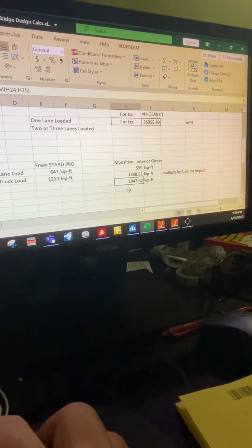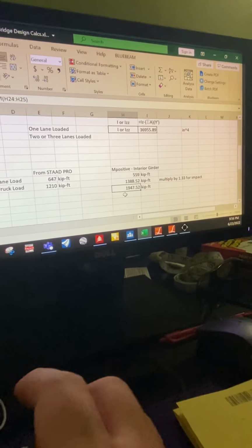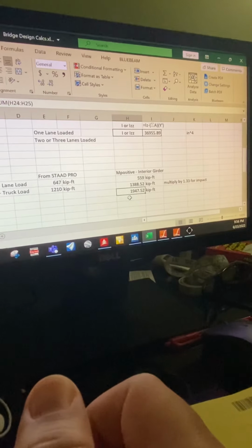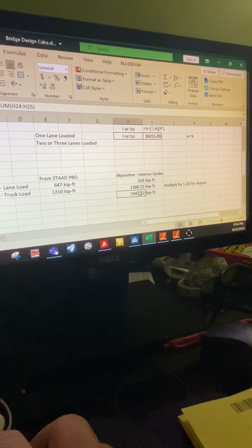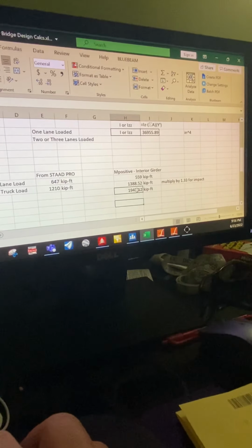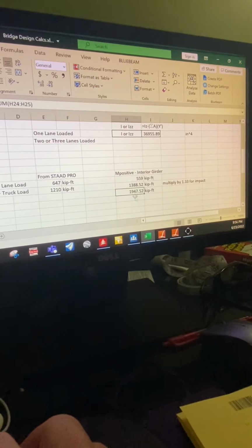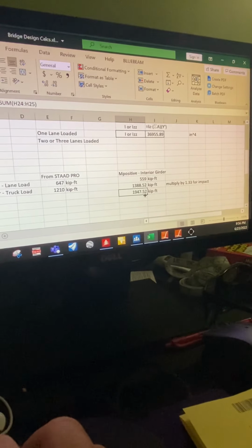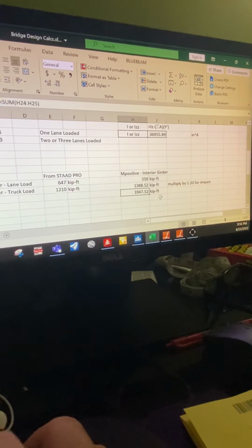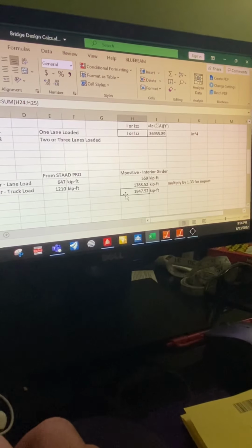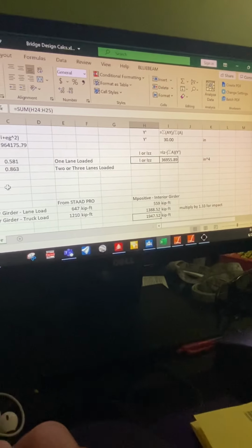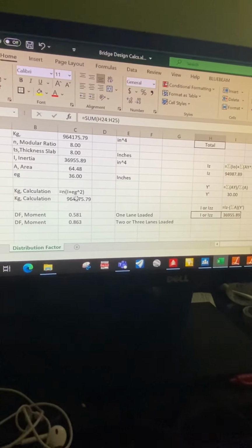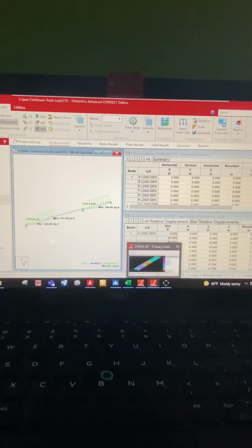Now this still has to be multiplied by 1.75, the factored load for live load. So multiply by 1.75, but for now we'll just leave it this way for our next calculation. So we got the maximum moment at 1,947 kip feet for a 2D analysis. That is given calculating the distribution factor and all. Now we make a comparison to 3D